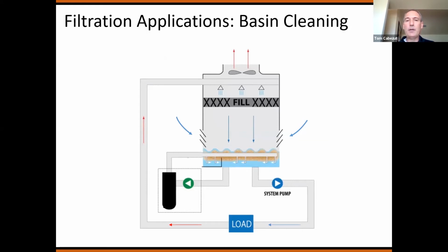The key is just to make sure that when you order it from the factory, that whatever filtration skid, which you can see here, is matched to the flow rate that they're requiring inside the basin itself. You don't want to go too large, and you certainly don't want to go too small because it will not operate properly within this basin.